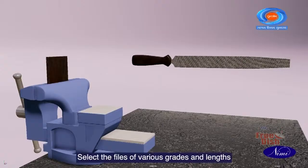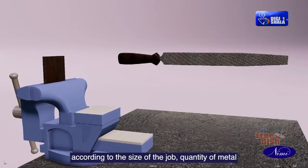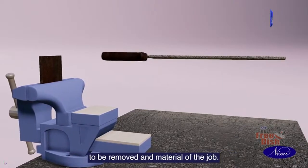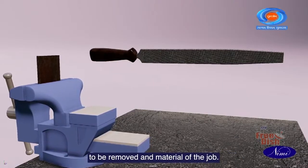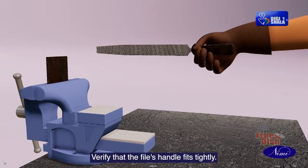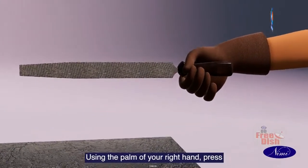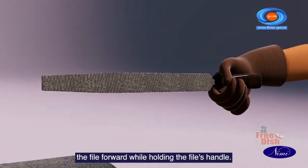Select the files of various grades and lengths according to the size of the job, quantity of metal to be removed, and material of the job. Verify that the file's handle fits tightly. Using the palm of your right hand, press the file forward while holding the file's handle.